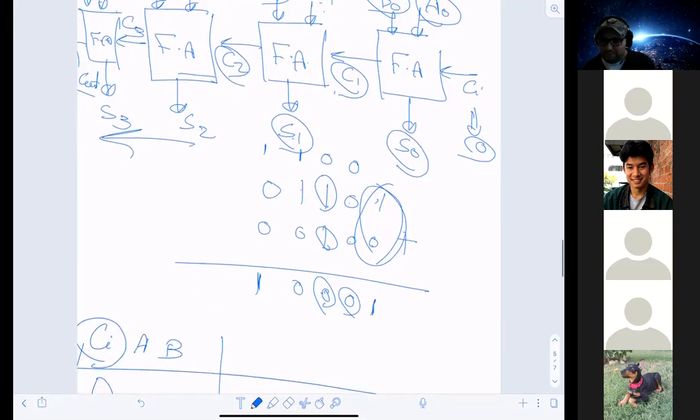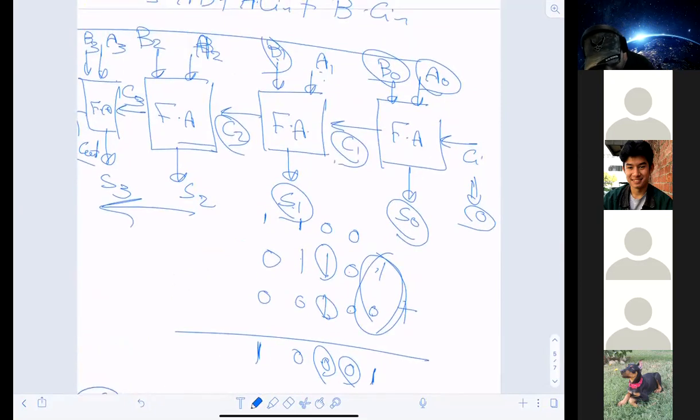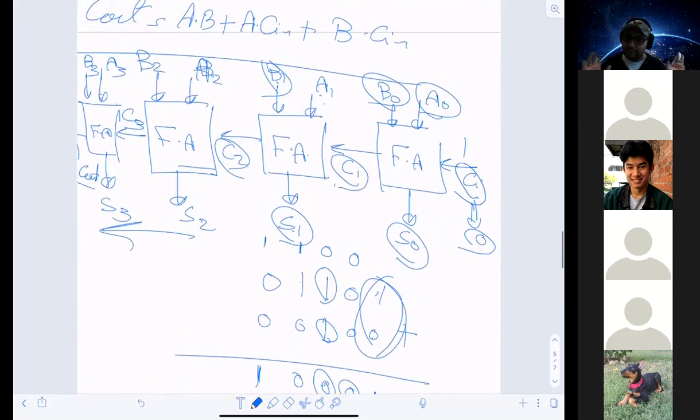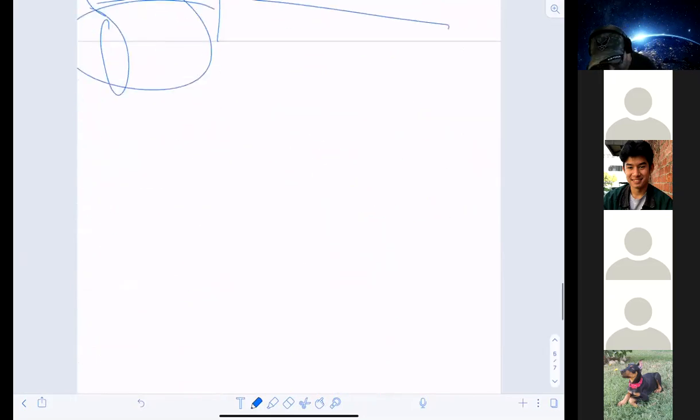So imagine the following. First of all, to perform subtraction between A and B, this circuit has to have 1 here, because it's going to be A plus B complement plus 1. Who will give me the 1? That's CI. I will turn it from 0 to 1, and then it will look into the second part of the table. Second, this B0 has to be B complement. You agree?